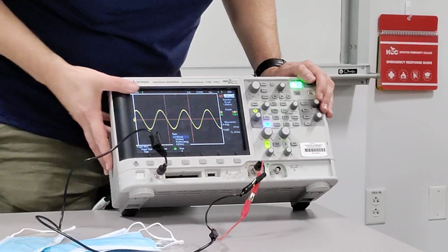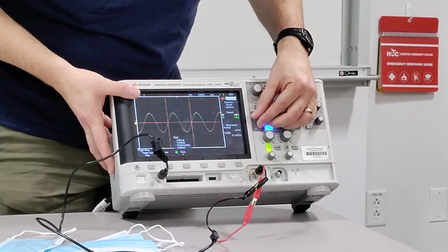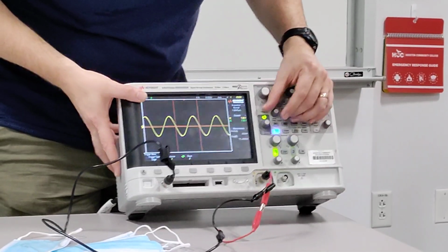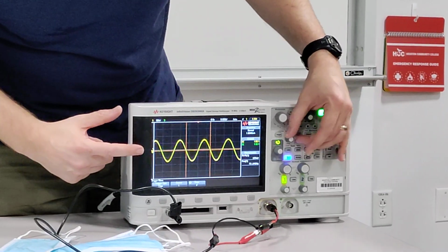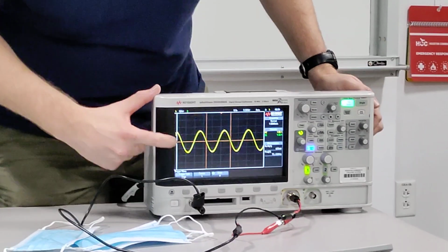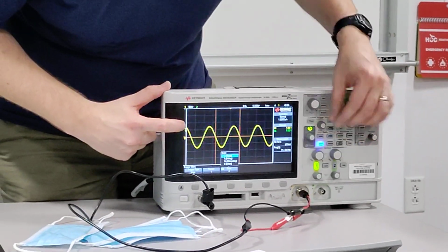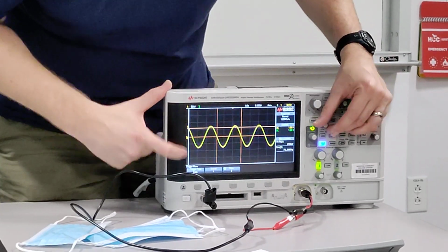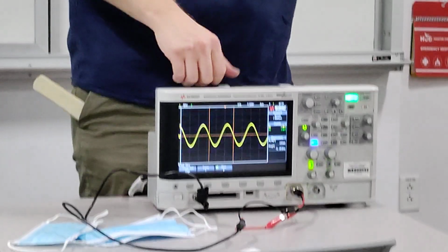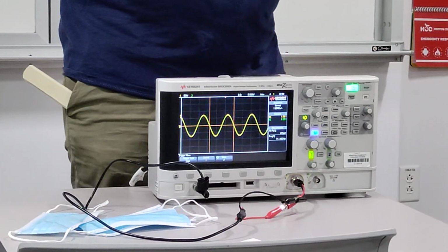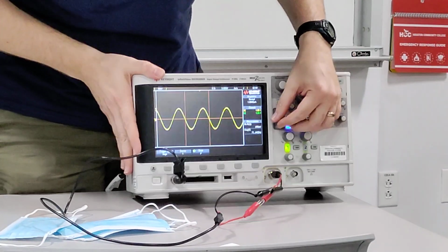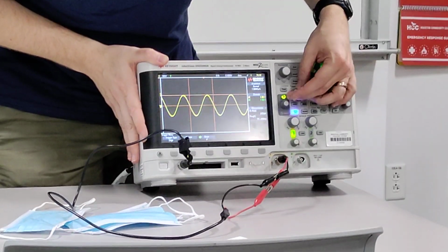And I can decide if I want, as I say, rising or falling edge. And I can raise and lower the trigger point. So you can see that line, maybe, I hope so, rising up from the middle. And once I go outside of the input that I'm sending to the oscilloscope, there's no longer a point where the trigger is being activated. So it's not going to know anymore how to line up these images. So I'll just show you that.